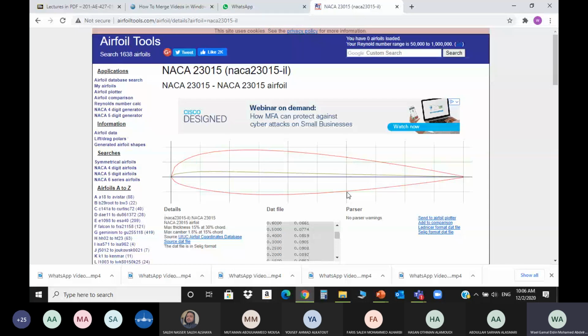Now, how do I know this height? In the airfoil X and Y here, it's based on the chord being 1. So for example, this height here might be 0.15. It's 0.15 because the chord is 1. How do I get the height? It's the difference between this point and that point, or you draw it to scale. Okay. So if this is 0.15, then the fuel tank maybe will be 0.12, slightly smaller than the 0.15.